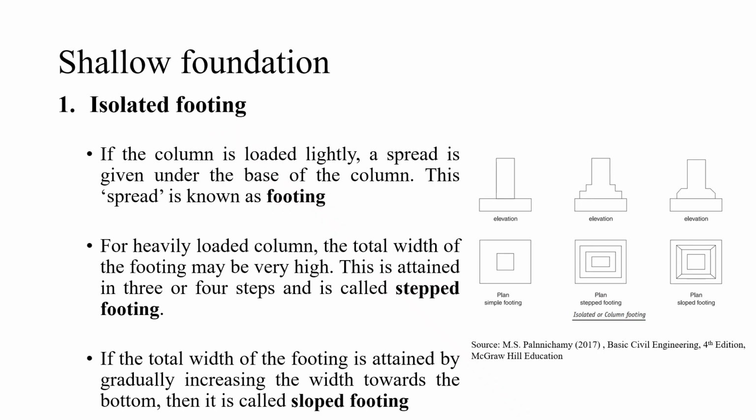See this figure. This is the individual column, and beneath every column you have a footing. And as I told you, if the load to be transferred is heavy, to bring the stress developed within the permissible limit, you will be developing a stepped footing. And you may also create this inclination with the help of a slope instead of a step.